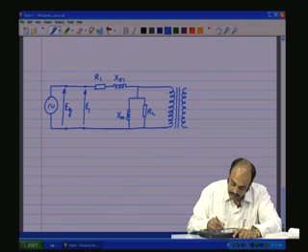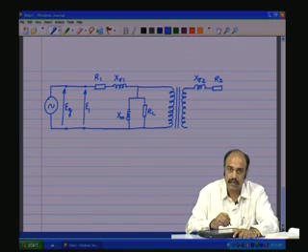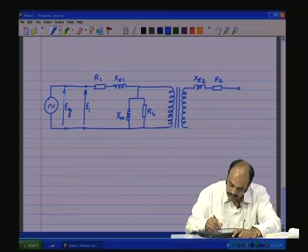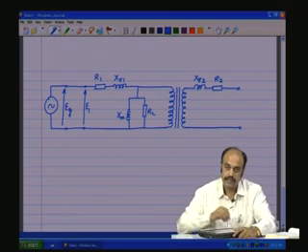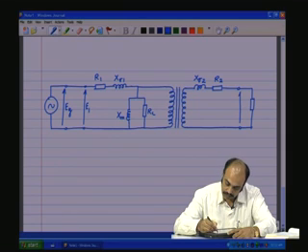The secondary of the ideal transformer contains the leakage reactance of the secondary. This is followed by the resistance of the secondary coil, N2 turns, and that gets terminated as the secondary terminals, and there we have the load across the secondary terminals. So, this would be our secondary.